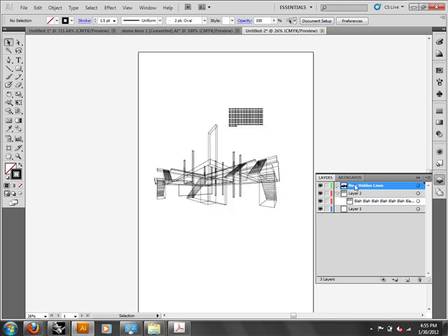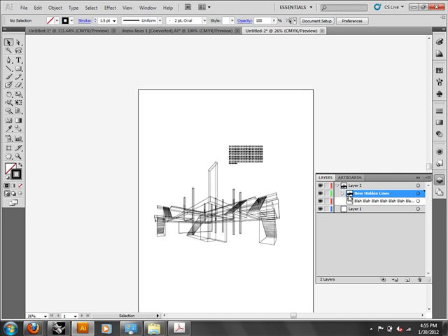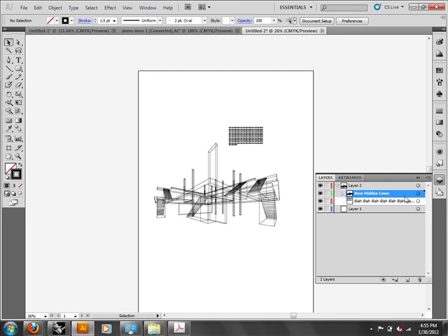One thing my class had trouble with was that you have to have the layer selected that you want to send it to, otherwise it doesn't go anywhere. So pick the layer first and then send it to that layer. Now I can make it a sublayer. I don't know why I couldn't send it to a sublayer before, but you can do that. You could have each one of your things have separate sublayers, and that'll work. But anyway, you should do most of your composition before you do your layout, and that'll take care of a lot of those issues for you.